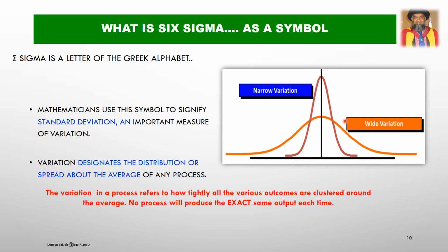It means the system is performing. If you receive exactly the same data every time, that means something is wrong. The data is frozen, the transmitter is not functioning, the measurement has issues, there's a calibration problem. So that is a different problem than the one that arises when data accuracy becomes a challenge.